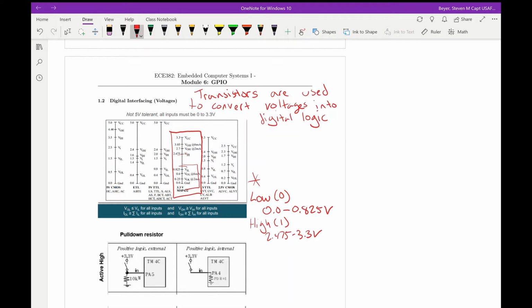It's important to know, when you're interfacing with digital logic and different embedded systems, what kind of voltages correlate to different logic, and to make sure that if the sensor is expecting 5 volt TTL, the processor can take that. The MSP432 has different ranges, so all the sensors have to be compatible with those ranges as well.